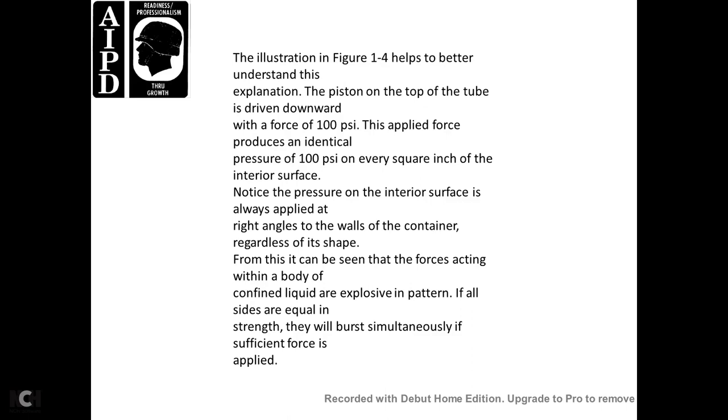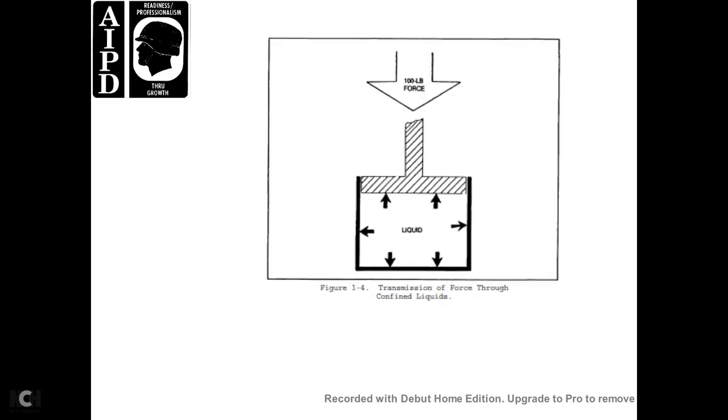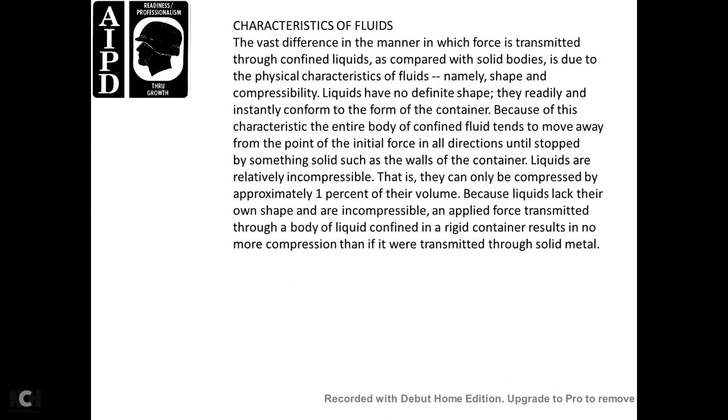That can be seen with the forces acting on the body of a confined liquid in an exploding container. If all the sides are equal in strength, they will burst simultaneously if sufficient force is applied. Figure 1-4 shows the transmission of force through confined liquids. 100 pounds of force is spread by the liquid over every interior surface.